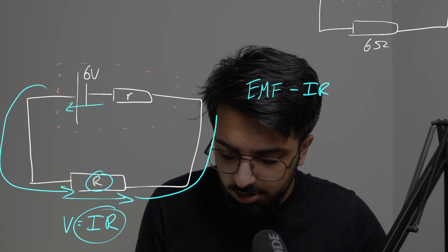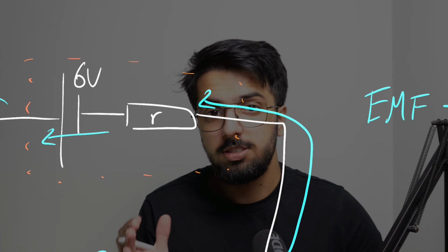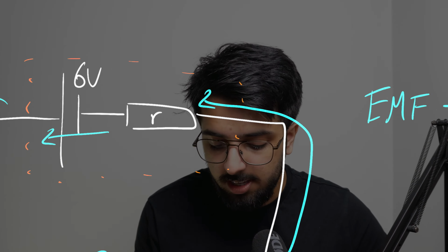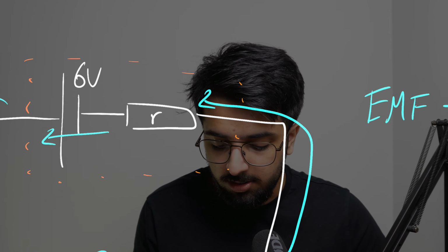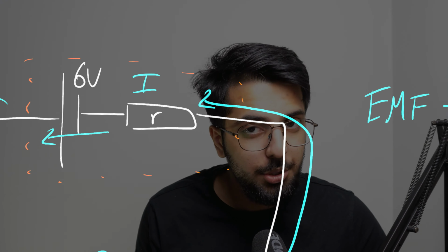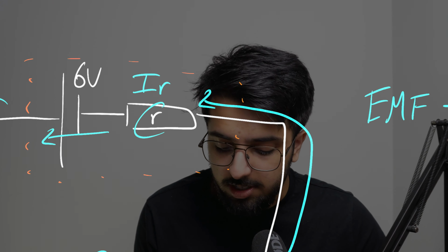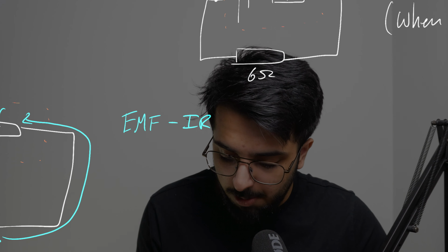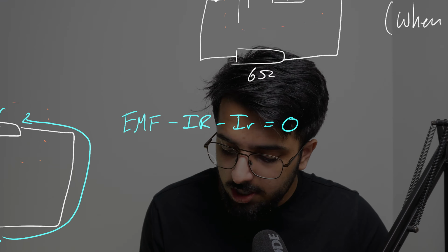And as the current continues, we're going to be met with this internal resistance. Again, this resistor does not exist in reality. This is just a model, okay? And the voltage drop across this internal resistor is going to be the current that goes through it multiplied by its resistance, which we can denote as little r. And so we can minus I little r, okay?